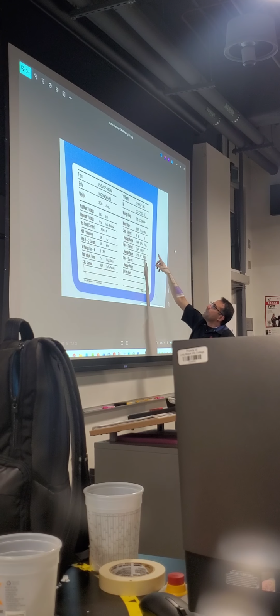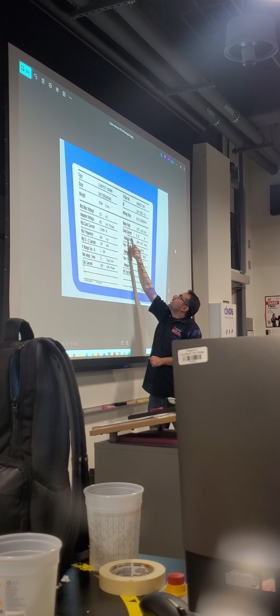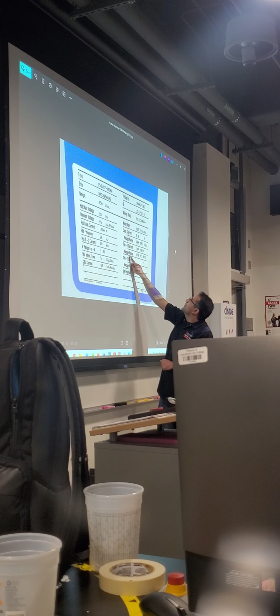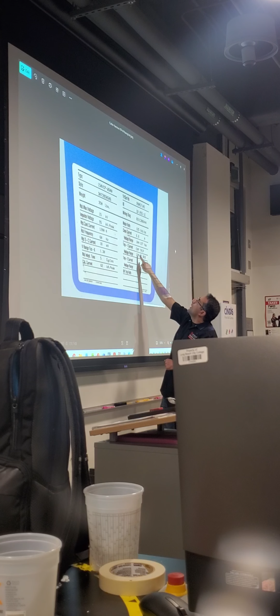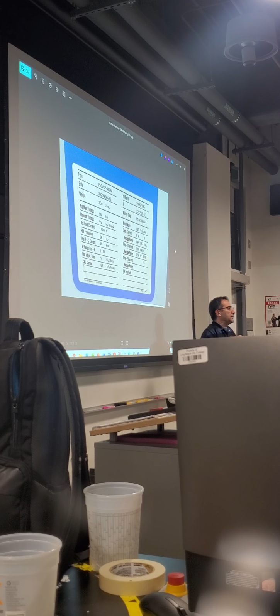Here, it's telling you the close current and voltage range, and tripping, trip current, trip voltage, and the motor volt. So you see 3 voltages. Let's start with the first one. Motor volt means charging: how much voltage you're supposed to apply to charge the breaker.